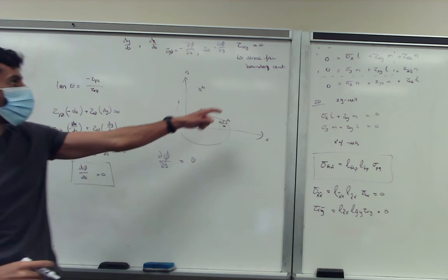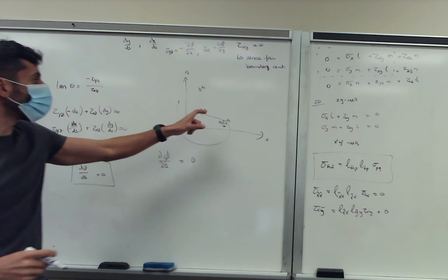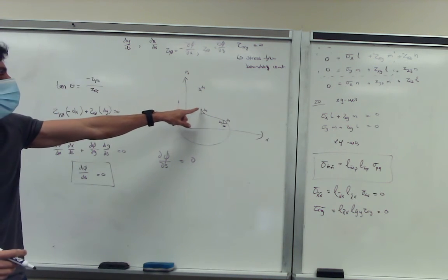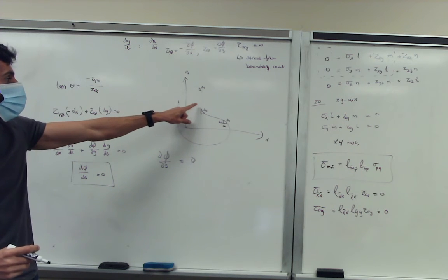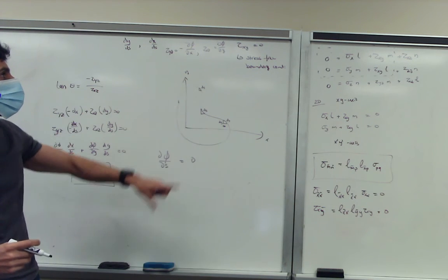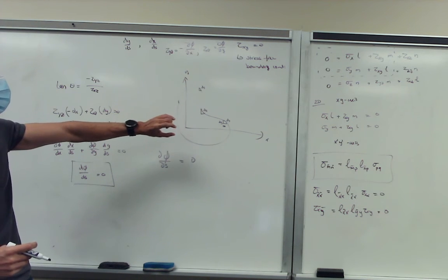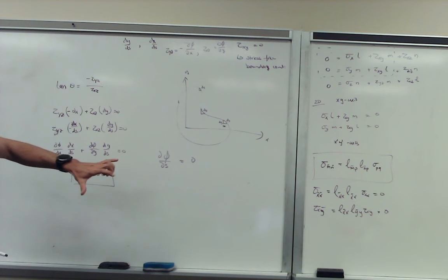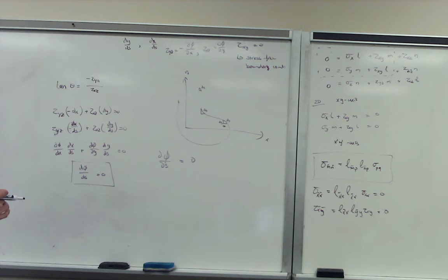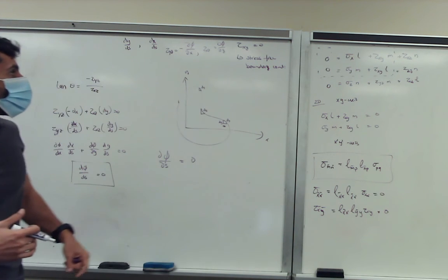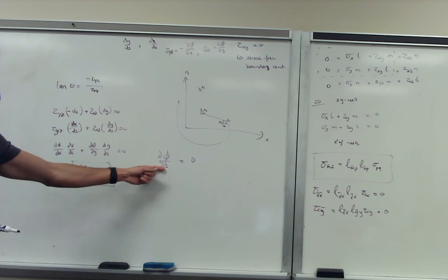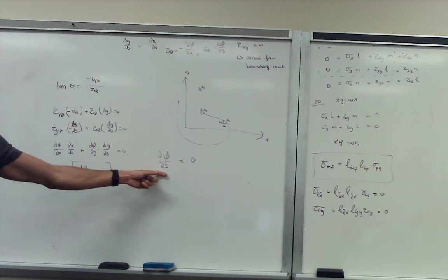This again goes to the fact that we stated here that if we look at the small differential element and we define our stresses x, y, and z on it, and we look at a 2D case, then we know that our stresses x and y are equal to 0 because we don't assume those stresses to exist, and that tau xy is equal to 0. We said this leads to a stress-free boundary condition, and this is defined by the fact that our function phi over the boundary must be equal to 0.